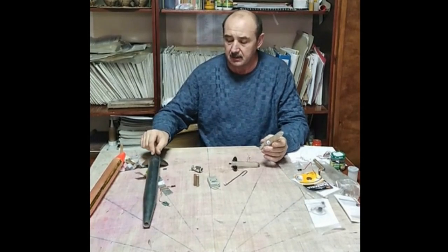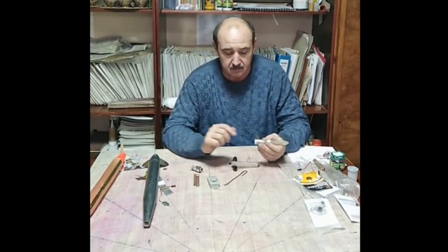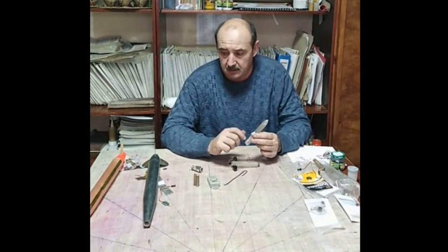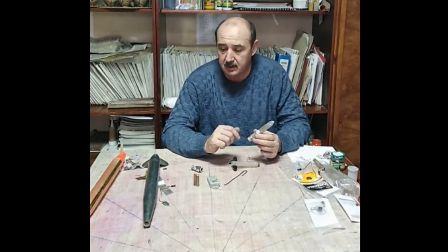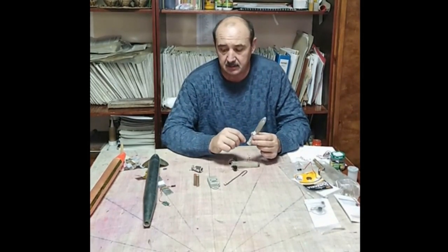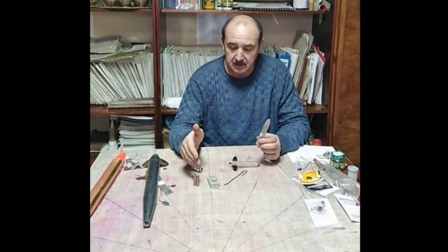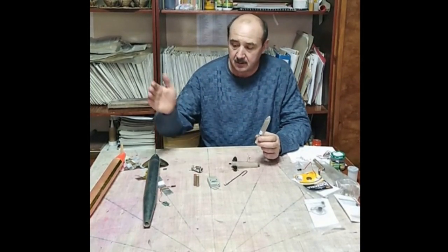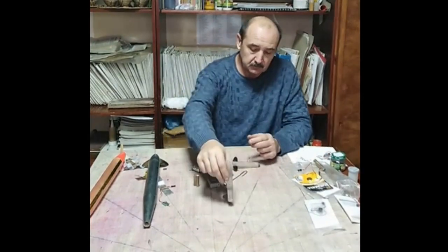Almost everything is the same except the hardness and weight of the models. The maximum weight of S1B can be 50 grams, and the weight of S1A can be up to 30 grams. And also the difference is in engines. Impulse is up to 1.5 Newton-seconds for S1A, and for S1B it is up to 5 Newton-seconds.